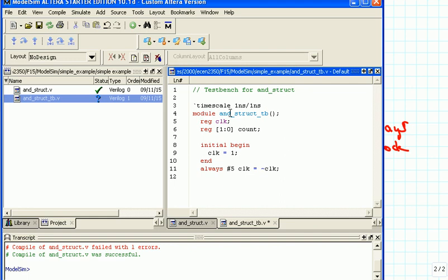And so now we have to initialize that count as well, because it's a register. It turns out that it's useful to initialize that to -1. And what's going to happen is that once the simulator starts, it will apply a clock to that, because we're setting the clock equal to 1. And so then it will actually go to 0. So the count will start at 0 if we preset it to -1 before the simulation starts.